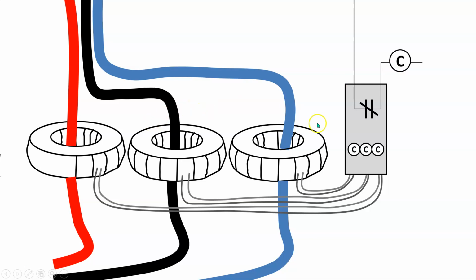So this is electronically done, obviously a little more accurate and instantaneous, but it's based on magnetic field, and these coils sensing that magnetic field. There's going to be a normal amount of magnetic field based on the FLA of the motor draw, but if that increases or gets a little bit too high, this is going to be sensing that, and it'll just trip out the coil.